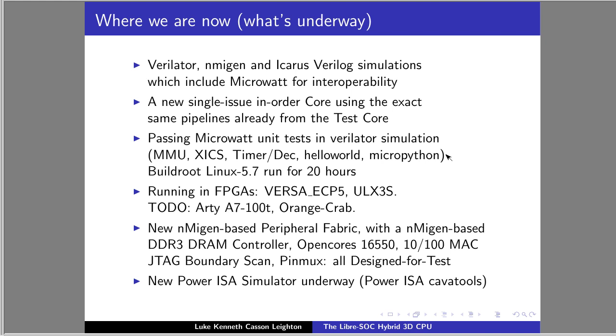You've done your core, and that's great, and it should be everything that you need. Well, no, actually, the peripheral fabric is almost as much design and development as went into your processor. And particularly when you're doing an SoC, you can have 1,000 pins worth of functions that need mapping. You can have 100 interrupt lines that need funneling down to that one external interrupt on your core.